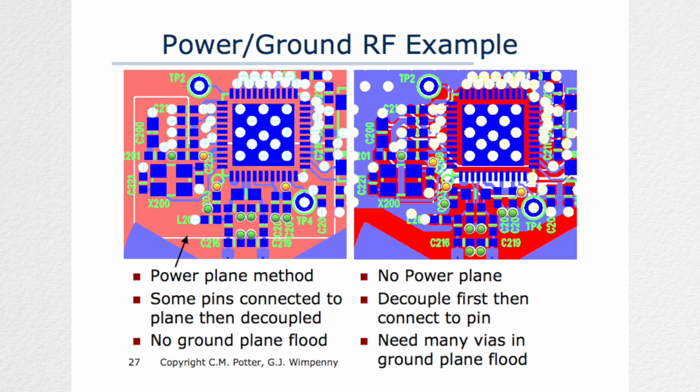So by visiting the actual pad of the decoupling capacitor before heading to the device means that there's less series inductance in the way, and therefore the effectiveness of the capacitance is much greater. Same thing over here. You can see that it comes from the underneath power track through that decoupling capacitor and then eventually out of there into the two pins of the device.